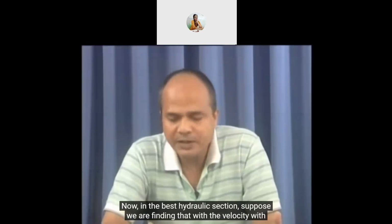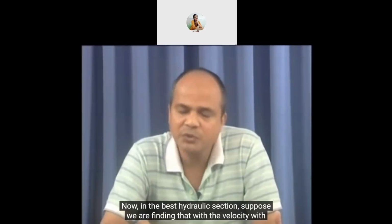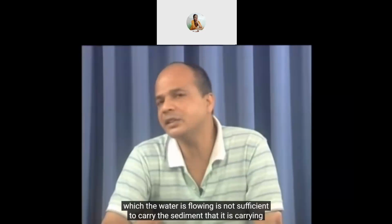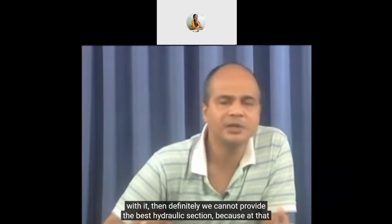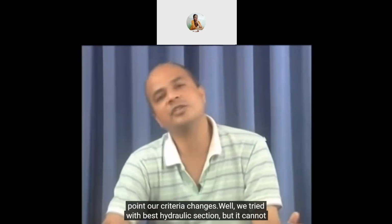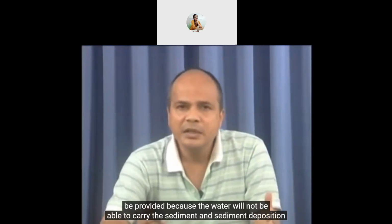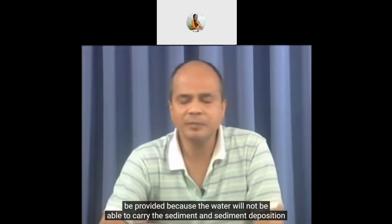Now suppose we find that the velocity with which the water is flowing is not sufficient to carry the sediment that it is carrying, then definitely we cannot provide the best hydraulic section, because at that point our criteria change. We tried with the best hydraulic section, but it cannot be provided because the water will not be able to carry the sediment, and sediment deposition may take place.